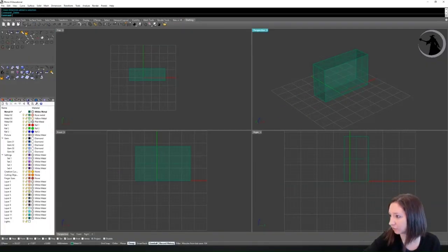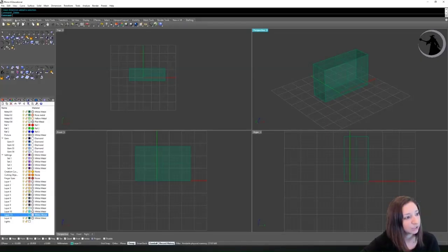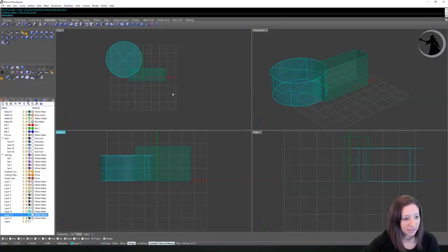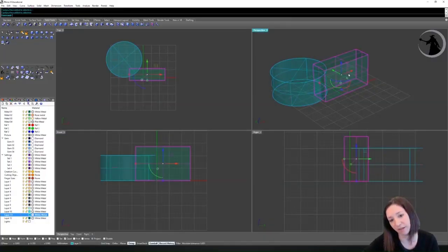I want to give you guys this file, which is this layout to make your construction plane be in millimeters, to make it smaller like this, which is about the size you need for jewelry, and also to give you all these different layer colors. These allow you to make objects in different colors, and then you can group things by their colors.